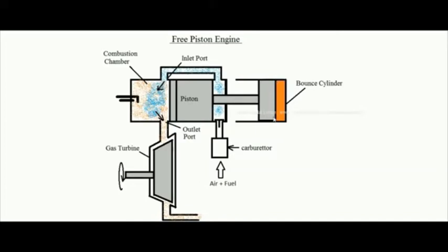And the third thing is, the bounce cylinder air is now fully compressed, meaning whatever energy is delivered by this piston to this bounce cylinder piston is converted into pressure energy of air. Now again the system has reached its initial state, that is, the bounce cylinder is containing pressurized air, and on the left hand side of this two-stroke engine piston there is fresh charge.